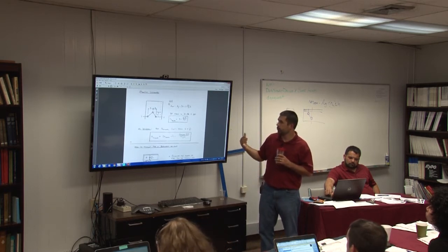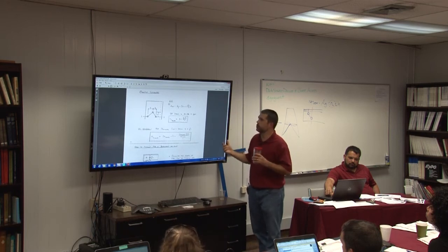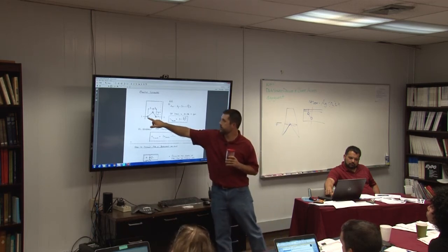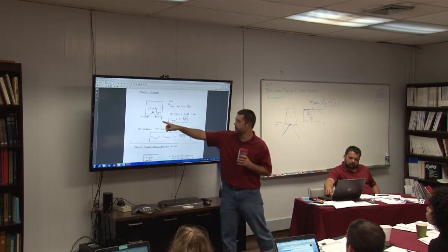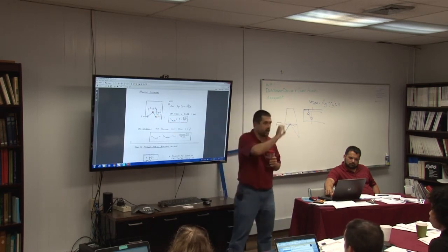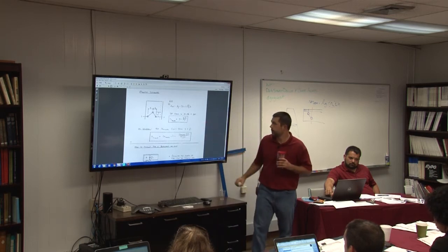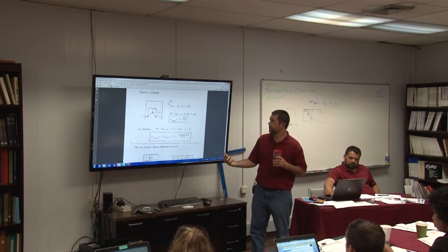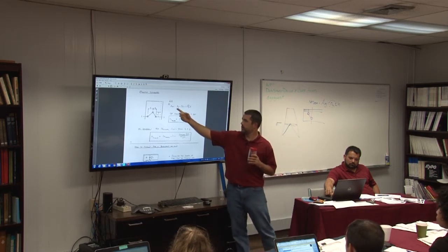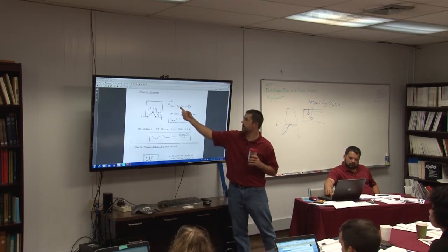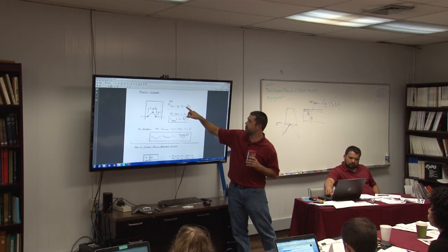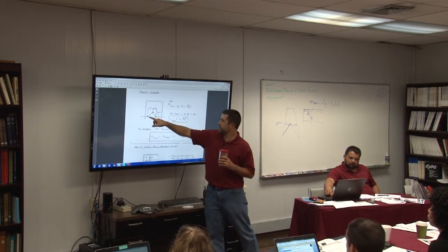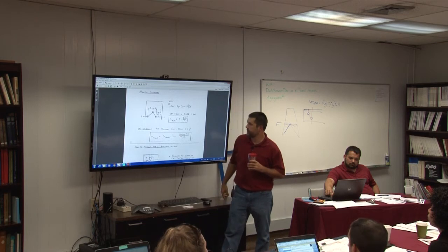I can repeat this calculation for 2 staggers. So you can have patterns that have a hole pattern like this, where I potentially have to stagger twice as I go through. And I can follow the same procedure. The actual net area is the gross area minus 3 holes, and then basically my minuses will cancel, I'm adding in 2 times the s squared over 4g.